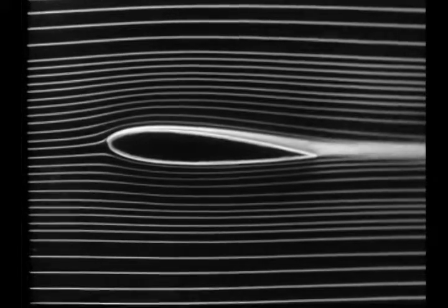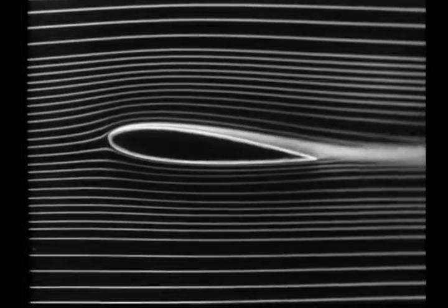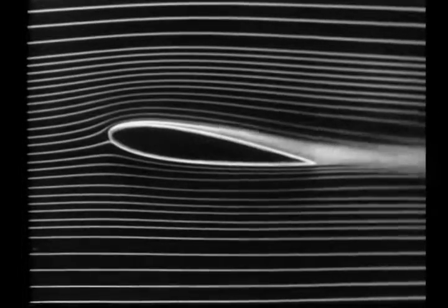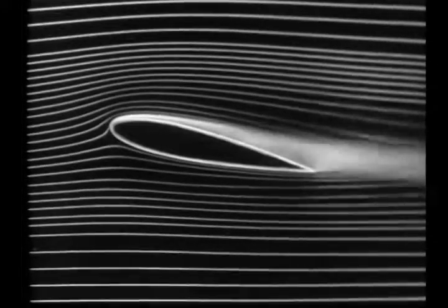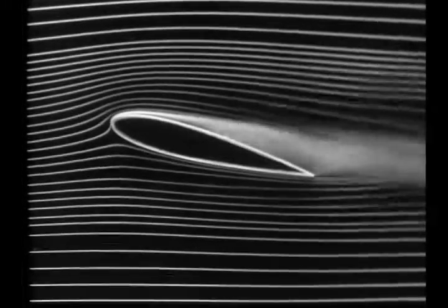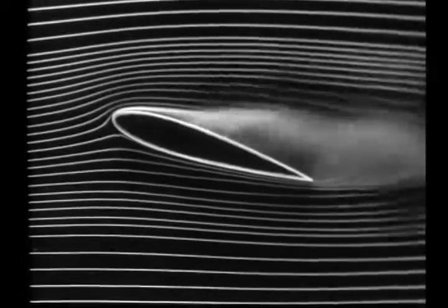In the laminar boundary layer, fluid mixing and viscous skin friction are low, but laminar layers are frequently unstable and result in turbulent flows, which involve much more rapid mixing, producing higher skin friction drag. Another example of the importance of the boundary layer is its ability to totally disrupt the main flow. The retarding and eventual reversal of the flow next to the surface of this wing in a region of adverse pressure gradient causes the entire flow to separate.